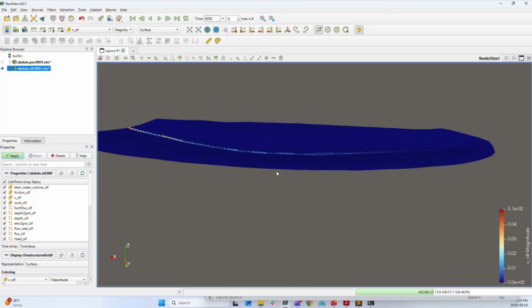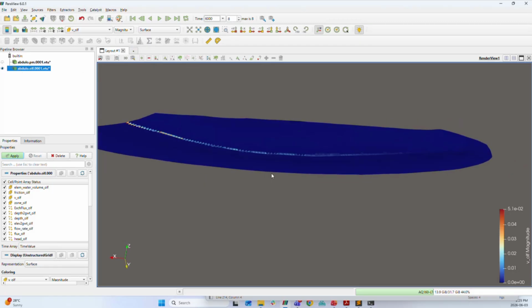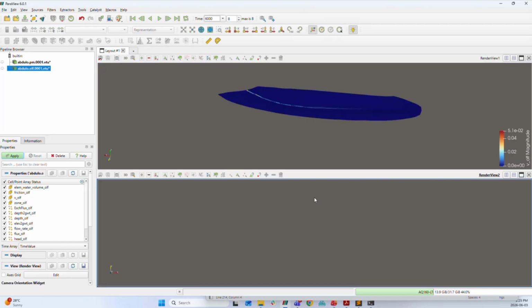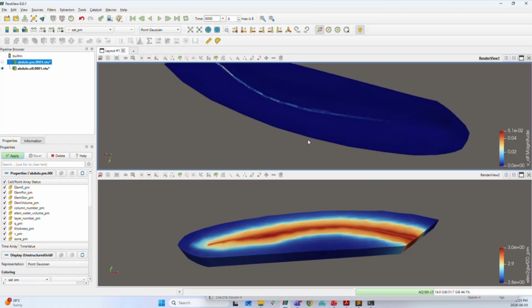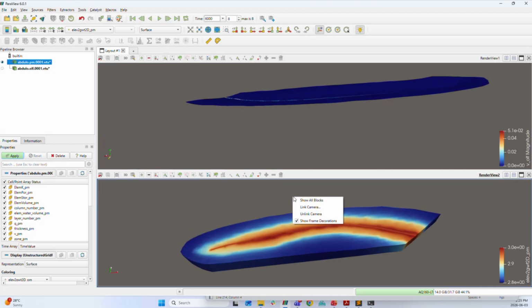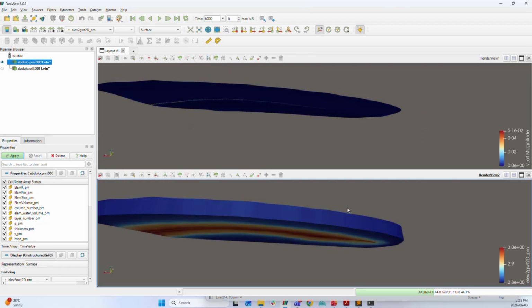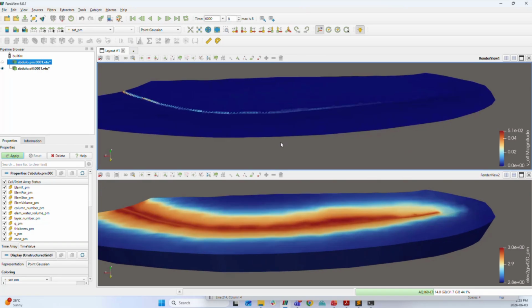In ParaView, I can also mix and match different frames. So let's say I want to show my surface data here, and I can create a new frame below with a render view. And while this one is selected, I can turn on my porous medium data. And maybe I want to tie these frames together so that they have the same orientation. So I can right click here and just easily click link camera and just click over to the next one. So now wherever I change the visualization in one of these windows, it will map itself identically over to the other one.